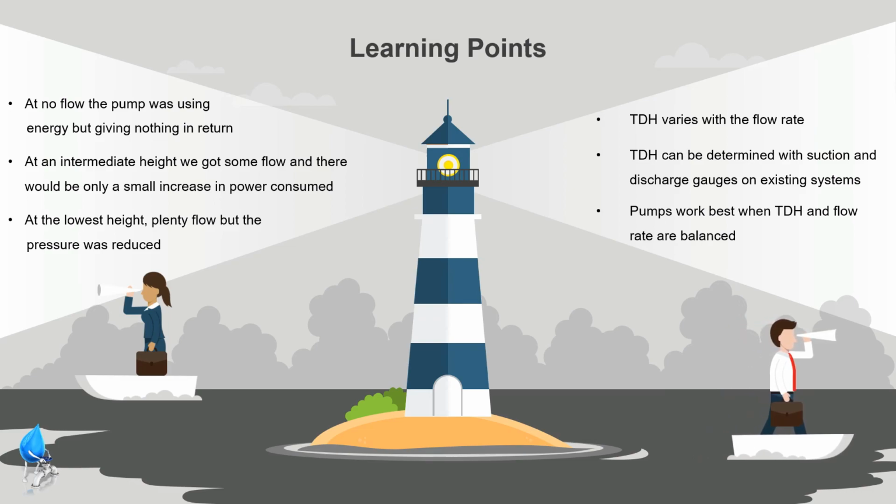TDH can be determined with the suction and discharge pressure gauges, and pumps work best when the TDH and the flow rate are balanced. The information published by the pump manufacturer will tell us what the pump's head versus flow rate balance should be.